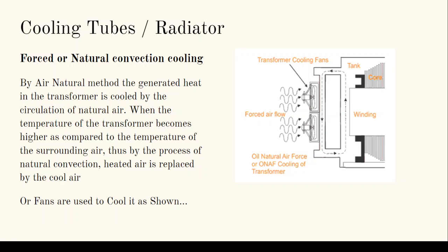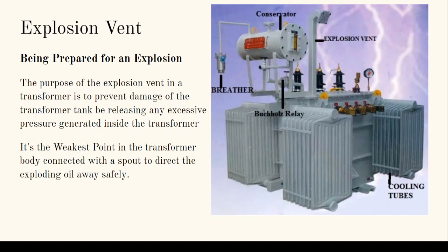So this is the forced or the natural way of cooling a transformer. You would have seen them in practical. These are the breakdown to say exactly what these fans do in bigger transformers when you have a distribution yard. So this is a simple distribution transformer. Let's look at the different parts that you might not see normally in diagrams.